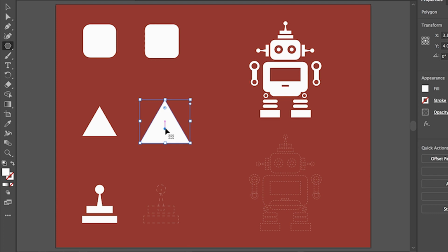Now the last type of shape you'll create is a circle. So press and hold on the Polygon tool in the Tools panel and select the Ellipse tool. Down here, drag to create a circle, and as you drag, watch for these hinting crosshairs, which mean a perfect circle. Release the mouse button when you see them, and the circle is roughly the size you see here.